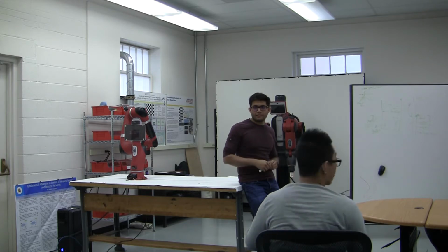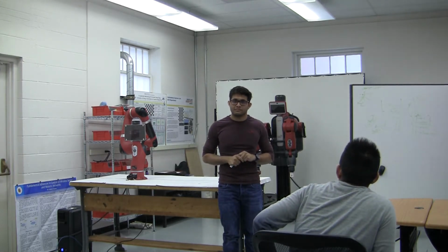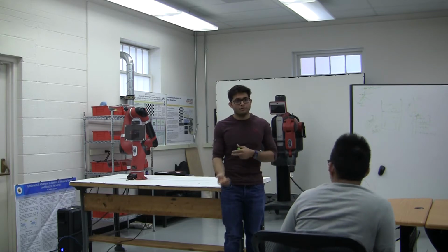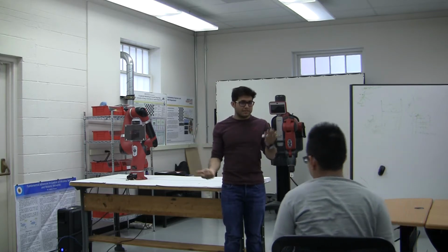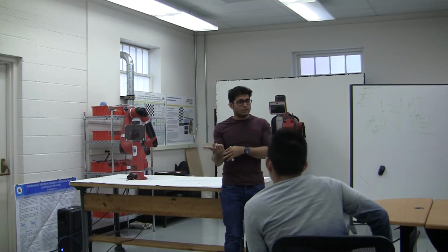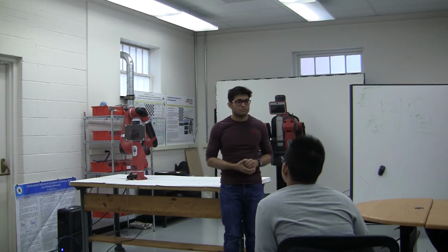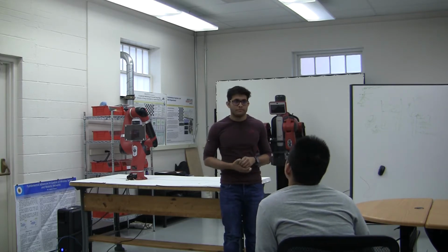Do you understand correctly, if your URDF is not properly set up, and let's say there's a camera, the camera runs into something, the robot is going to lock itself because of the force sensors. If there's an external force, they have the dynamic server again. It looks at the forces all the time, right? And if it exceeds the limit, it stops. So it will do that for sure.